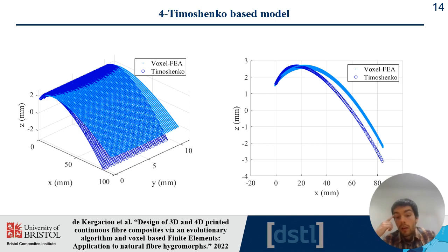This will have an effect on the actuation, because this material will stiffen the structure in the length direction, and our model is capable of accounting for it. The Timoshenko beam equation is not capable of accounting for it, and this is one of the sources of discussion that we consider in order to explain the difference between these two models.